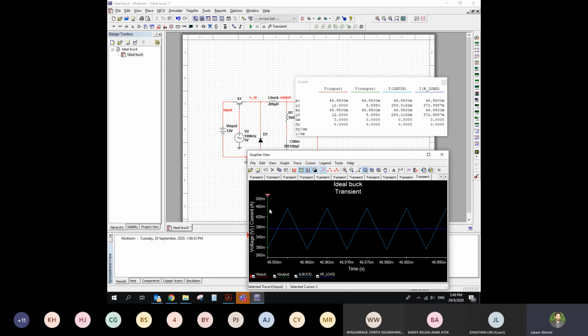So it's 0.16 ampere, as we found before. The impact on the peak to peak is the same as before: 300 to 460 is 160 milli, and 160 milli divided by 1000 is 0.16 ampere. So the peak to peak ripple is exactly the same, but the total current has been reduced.